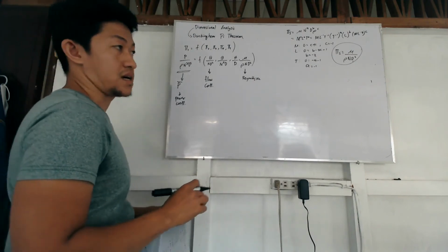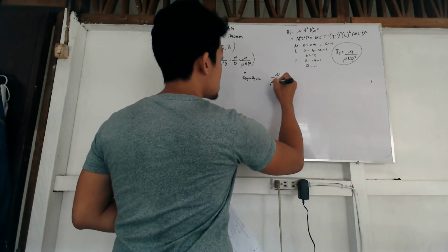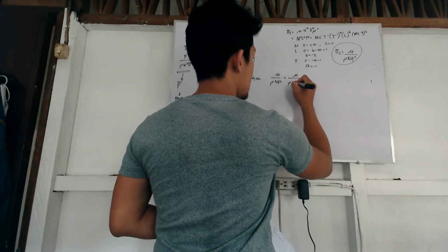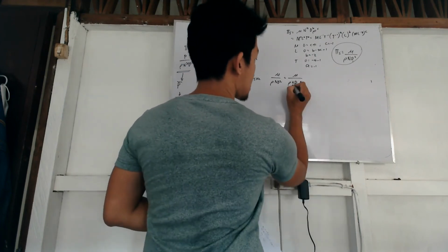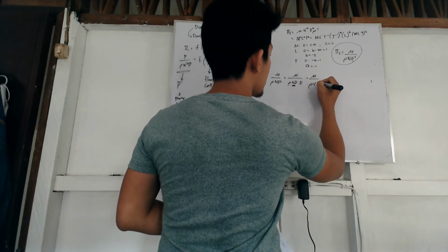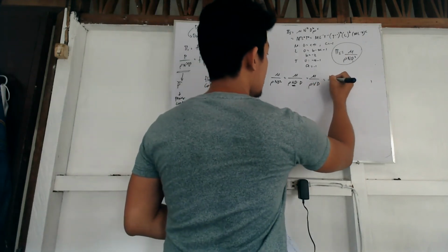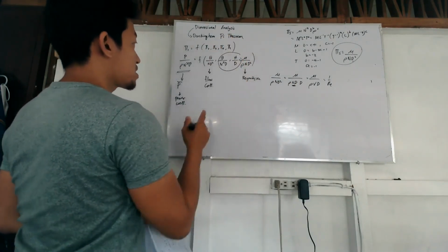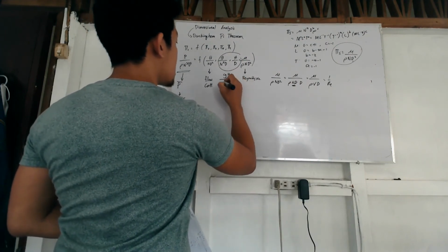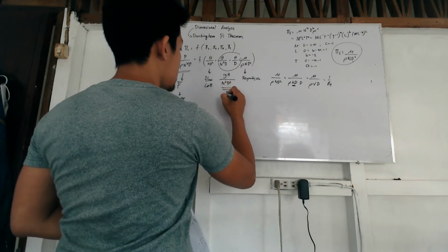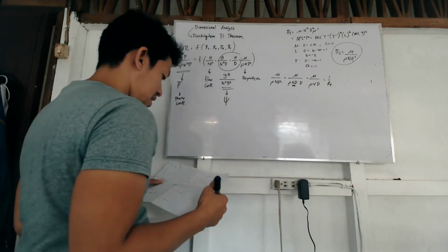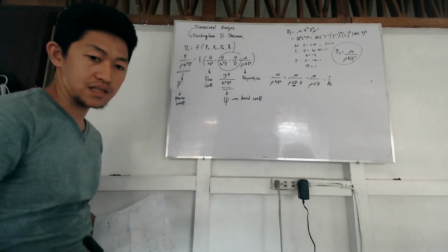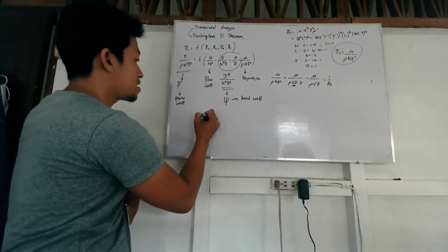It is the Reynolds number, yeah. Mu over rho N D square is mu over rho N D, and D. This term is velocity, no? So, D V rho over mu. So, it is the inverse, 1 over Reynolds number, so it pertains to the Reynolds number. These two you can combine. So, G H over N square D square. So, this you call the head coefficient. Head coefficient.